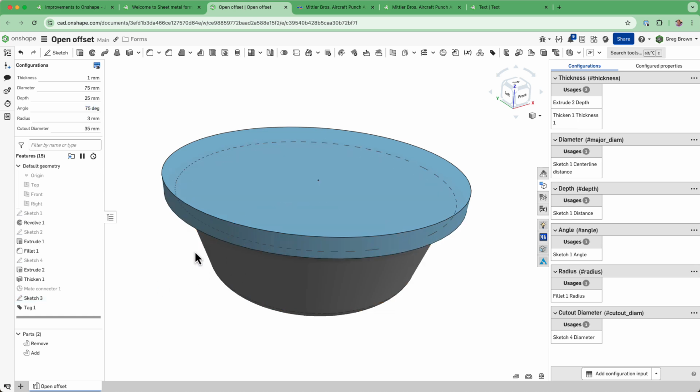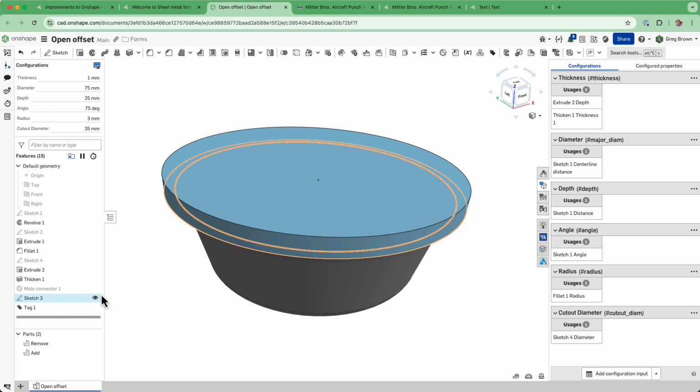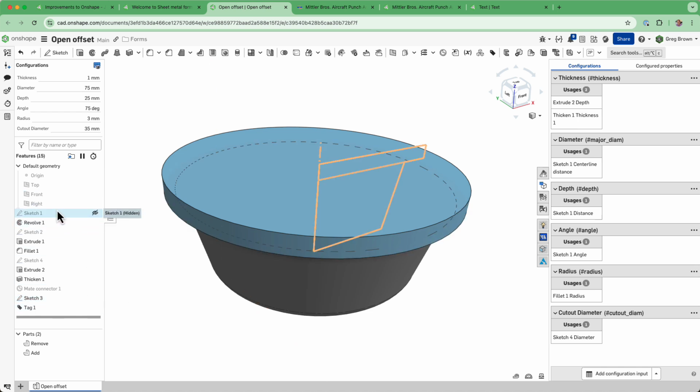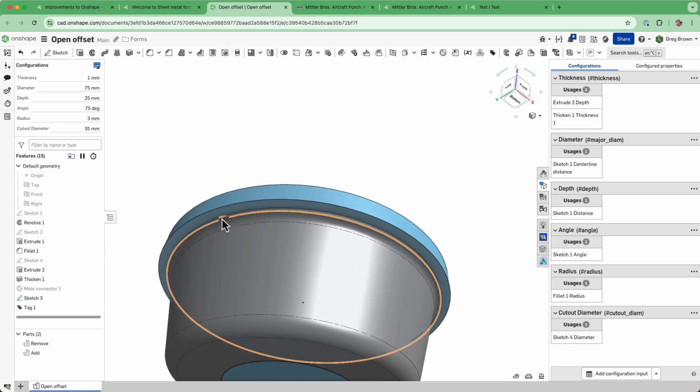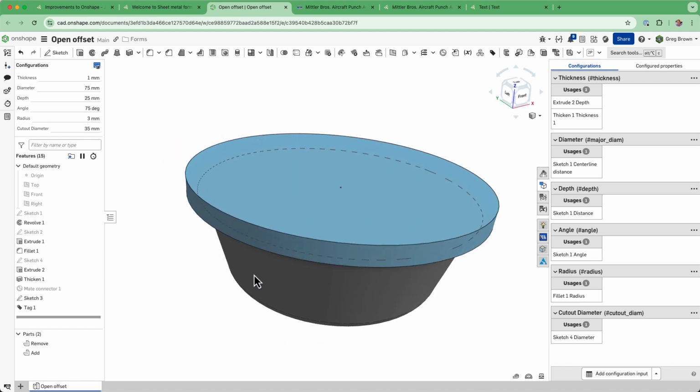The next thing you definitely need is a sketch, which is going to represent the shape that you see in the flat of the form feature. So typically, if you have one already, which is convenient, from the top view, which I don't, you can just create another one and use some edges that are convenient for that sketch, which is what I've done here.